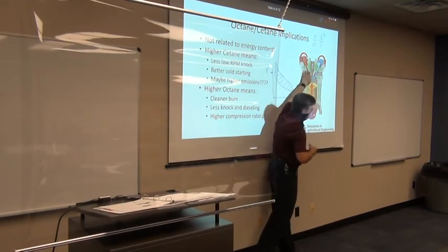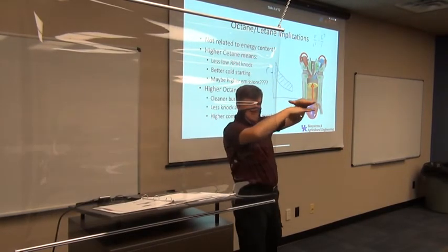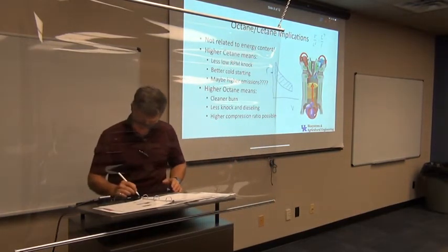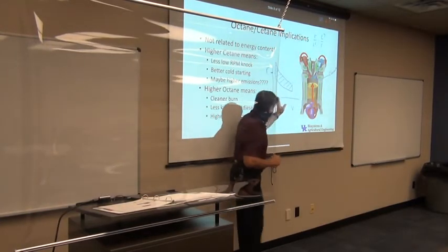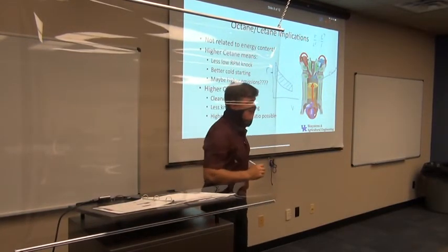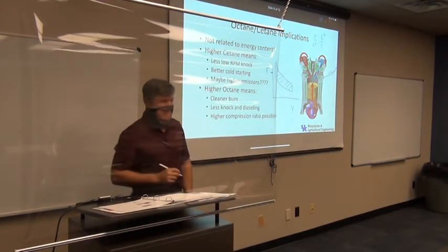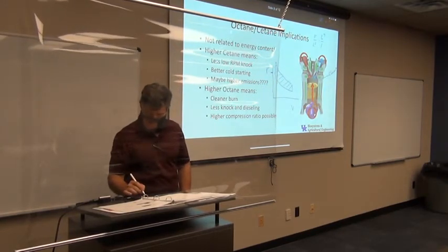What do we call this volume up above that piston when it's all the way to the top, what's left up there? We have a name for that. The clearance, yeah. So that volume that's left on the top is the clearance volume, right? So where's that on the PV curve? Where is that on the PV curve? So volume goes from here to here.